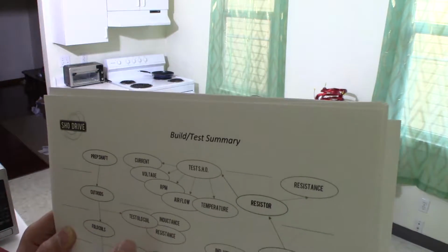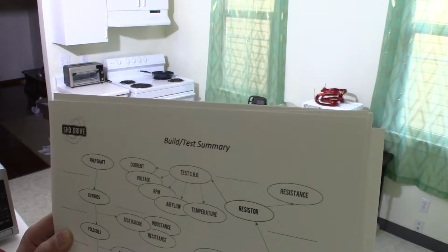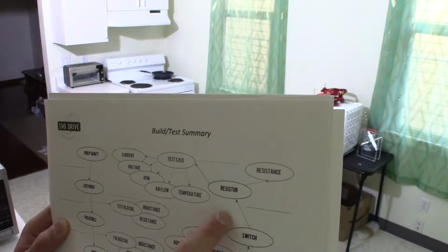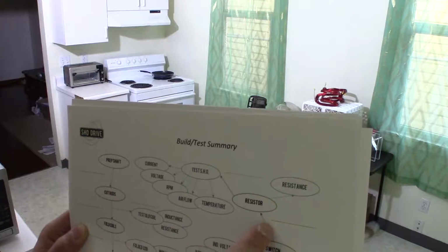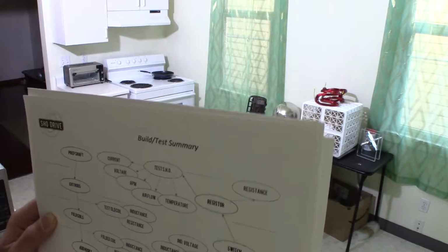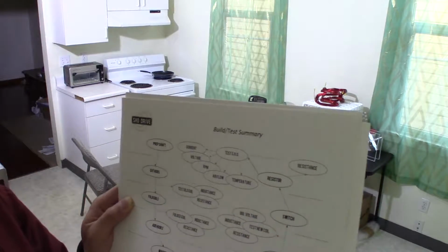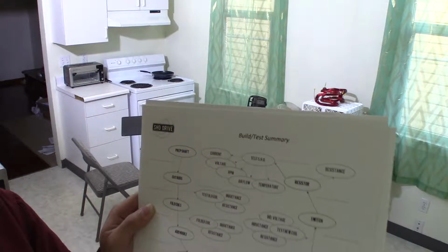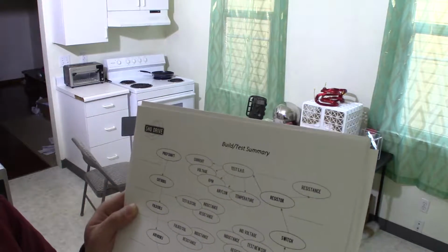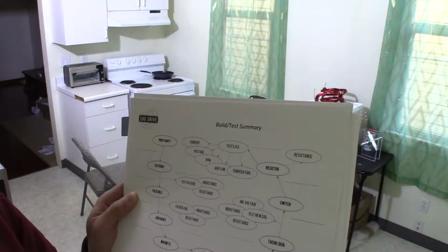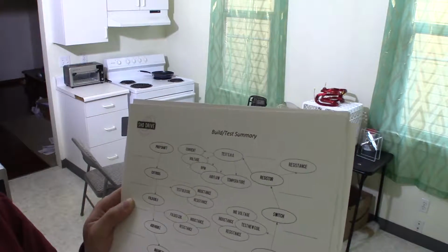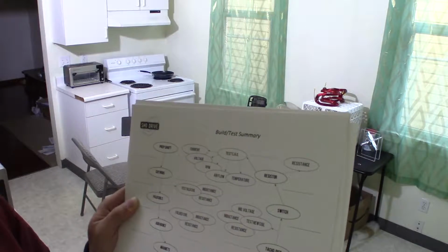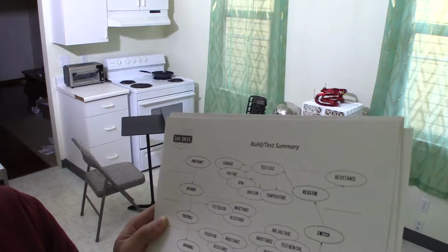We're going to test our old coils, inductance and resistance, folded coil inductance and resistance, new coil inductance, resistance, and induced voltage, and go to test the resistor in line with the switch, so that way we can have a consistent resistance-based voltage drop measurement. So resistance times current gives us a resistive voltage drop. As long as our resistor is consistent resistance that doesn't change with the current that much, then we should be able to calculate that appropriately.